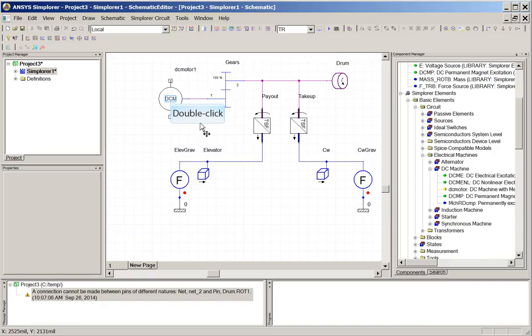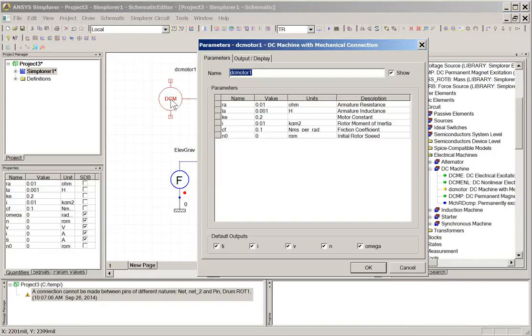Now I'll double click on it, and where the data comes from is later in Gross's textbook in chapter 9. He takes up this example again and specifies a specific 75 horsepower motor to run this elevator system. And the data comes from table 9.4. So for this motor, I'm reading some of these parameters right out of table 9.4. So the armature resistance is 0.2038 ohms.